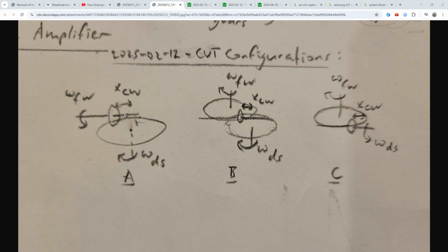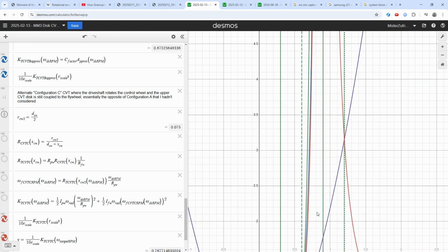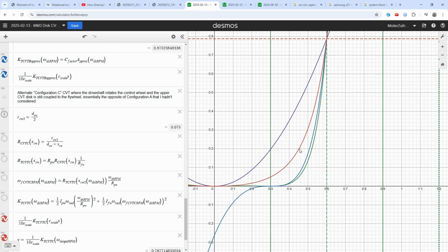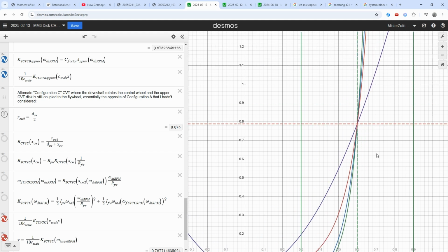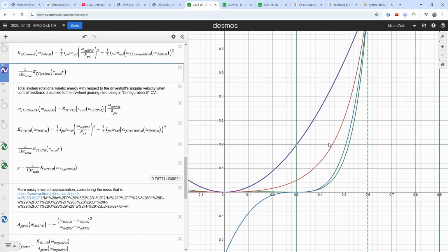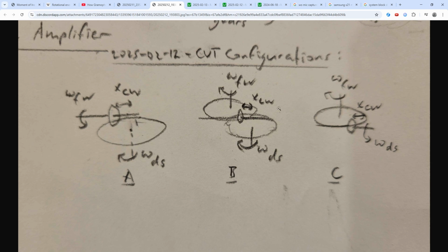So in this case, basically we're only controlling the lower bound using this pole, while here we're only controlling the upper bound on the speed. So this I've represented with that red graph that you would have seen. As we increase in speed, the flywheel can accelerate indefinitely, and we'll never exceed this upper bound, but we're allowing it to exceed the lower bound here, even while the flywheel is still spinning, like so. With that arrangement, you can see that it still performs a lot better than the plain fixed ratio flywheel, but it's not as good as the bidirectional system with 2 discs.